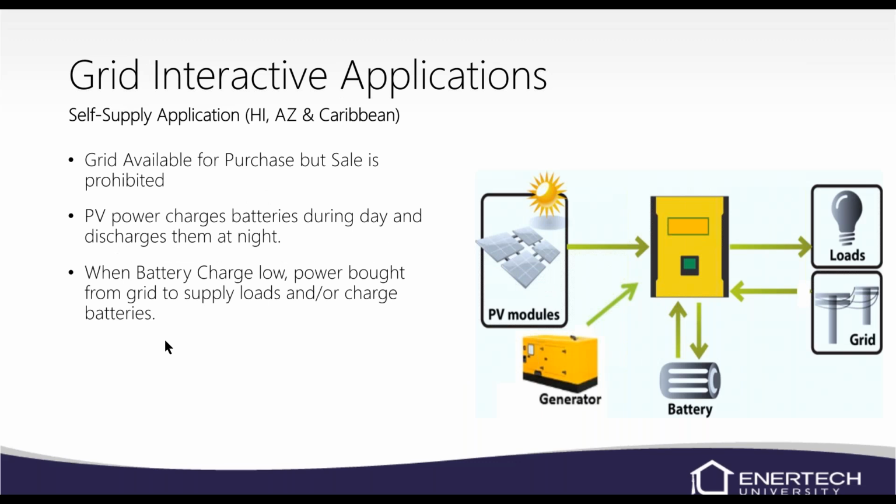Again, here's that little bit better picture of the grid coming into the inverter, your PV modules coming into the inverter, and your batteries hooked up as well. The grid is available for purchase, but sale is prohibited. So in other words, we're not selling back to the power company. So you can see in Hawaii, Arizona, and most of the Caribbean, they don't buy it back.